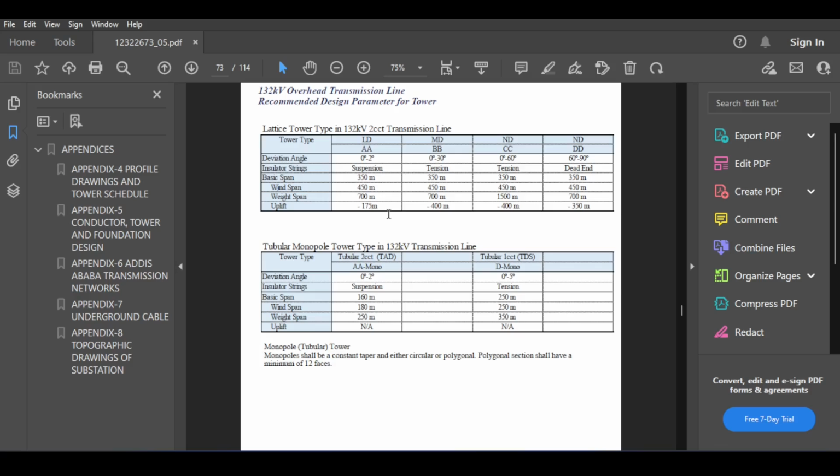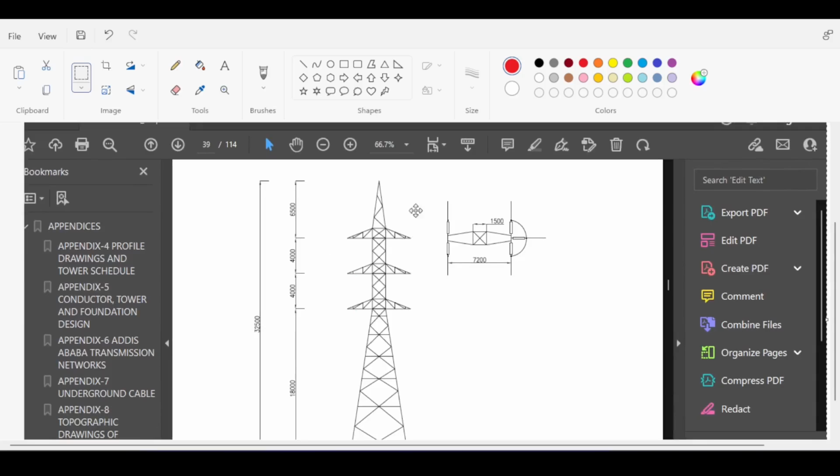You will say, okay, I have never designed this before, so how can I do that? And this is where my advice comes into play. You have to quickly research and understand the basic terms and use your engineering knowledge to use those terms to your advantage. It's a steel structure. It doesn't matter what the name of the steel structure is, lattice, tower, whatever. To design a steel structure, you know from experience that you need to know what the loads are, what the dimensions are, and any extra design considerations you need to take into account. And this is done by a quick research.